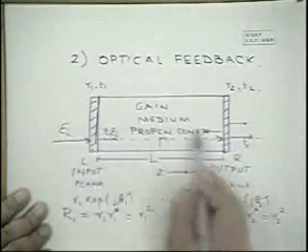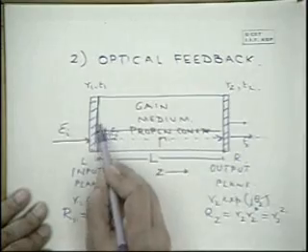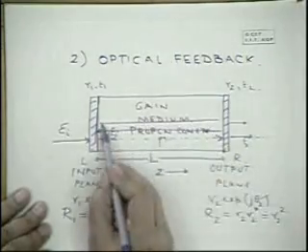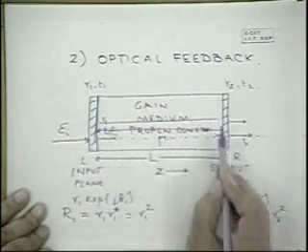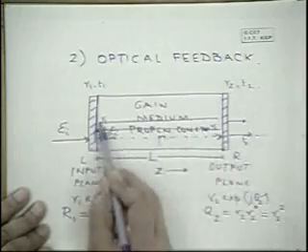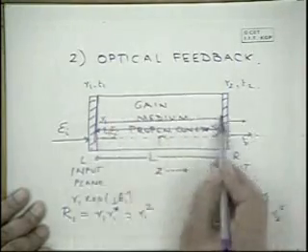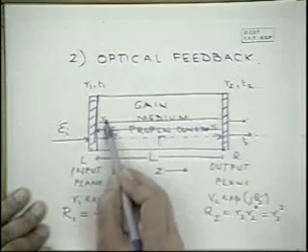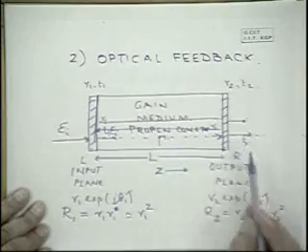This first one is T1 T2. Then this beam will come back here, it'll be reflected here, and then reflected here will be R1. The amount reflected here is R2, here R1, and it'll be transmitted again. So each time it undergoes reflection, it'll be R1 R2 into e to the power minus twice gamma L. Is that clear?